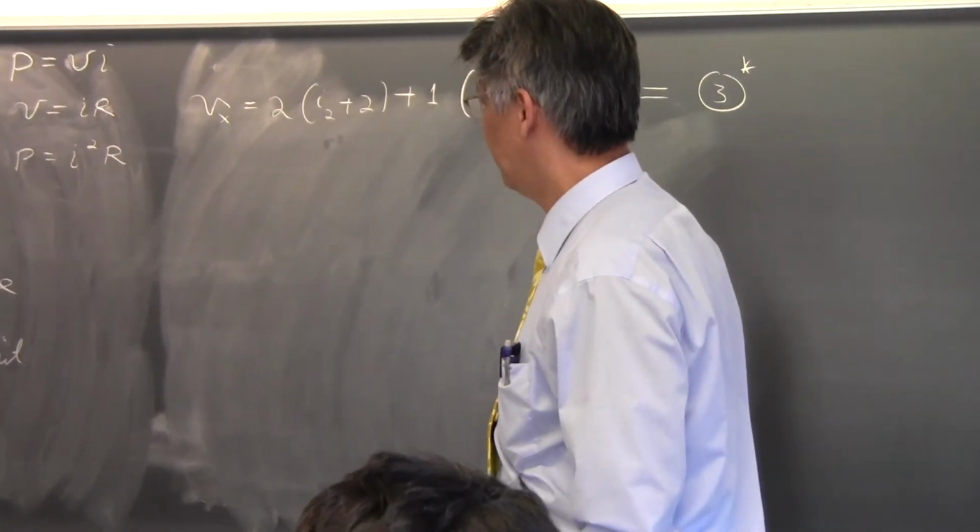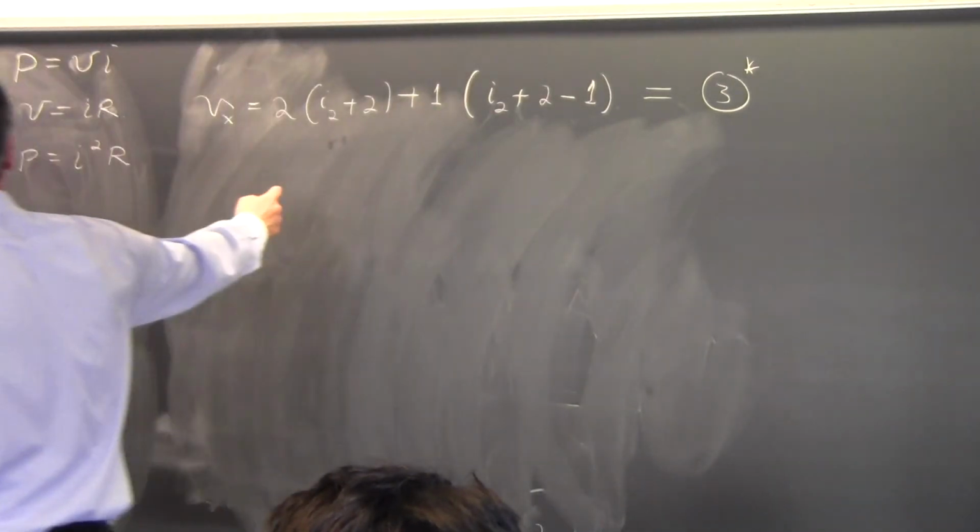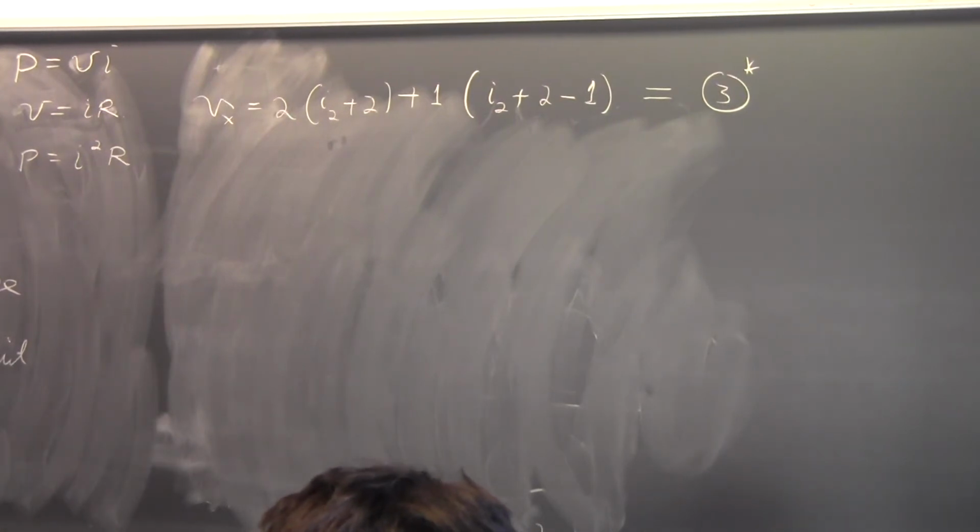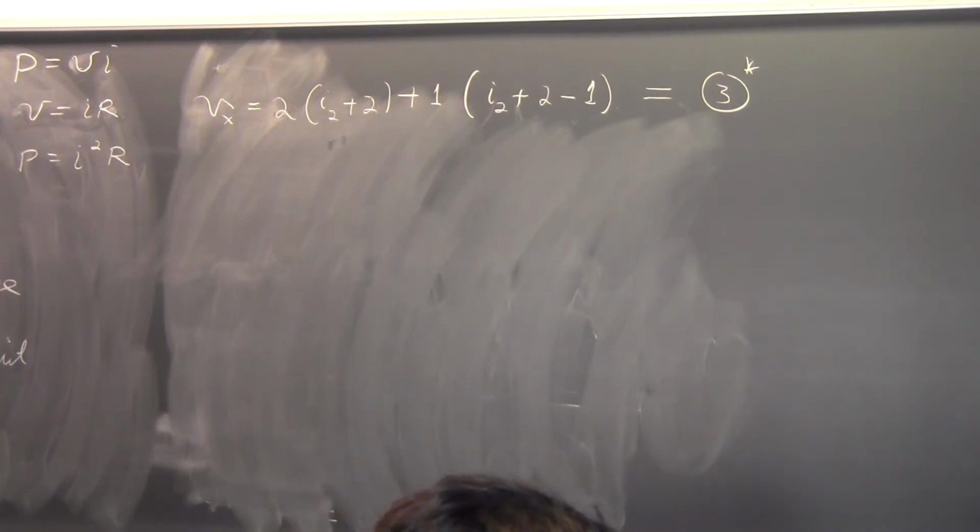Okay? And now if I plug equation 3 into equation 2, and again write I3 in terms of I2, then I have two equations and two unknowns. And I can easily solve for them. Can you see that? We plug that equation into the second equation and make sure that whenever I see I3, I replace it with I2. I have two equations, two unknowns, and you can say that those equations come from a super loop and this small loop over here. Okay, two equations and two unknowns. That's another way of looking at this problem.